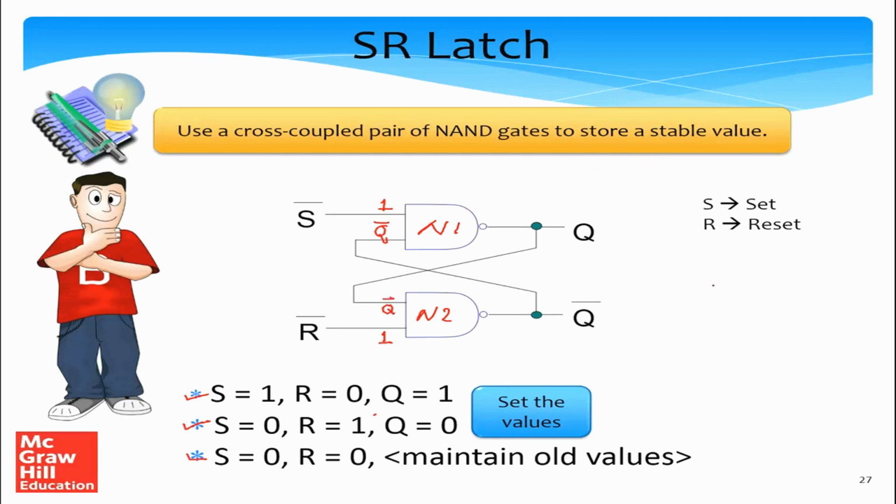So the question is, what is 1 and Q bar, right? And the entire thing complemented. So this is a NAND of 1 and Q bar. So one thing that we can see is that in a NAND gate, or maybe, let's do one more thing using the De Morgan's laws that hopefully we all know. So De Morgan's laws basically say that A and B NAND is A bar or B bar, A complement or B complement.